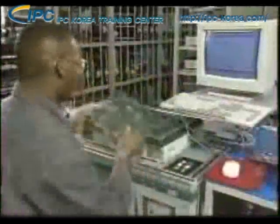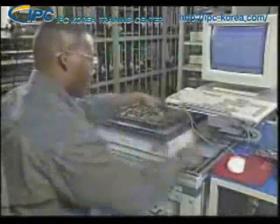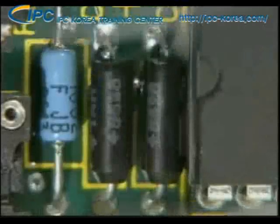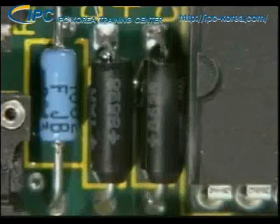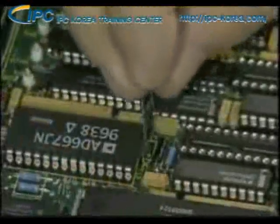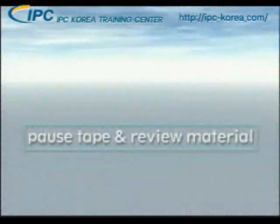When a component is not oriented correctly, the assembly won't function as intended and will fail electrical tests. When a component is inserted with polarities reversed, the component can actually be destroyed. There may also be damage to the circuit board and other components. The result can be costly repair work or even a scrapped assembly. Let's stop for a moment and review the material we just covered.